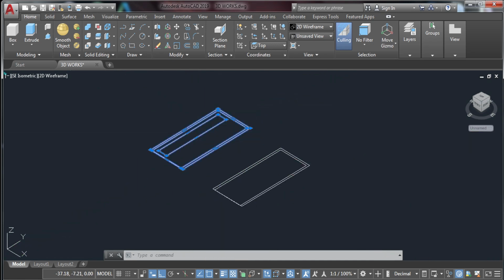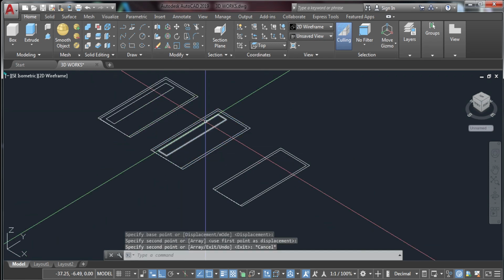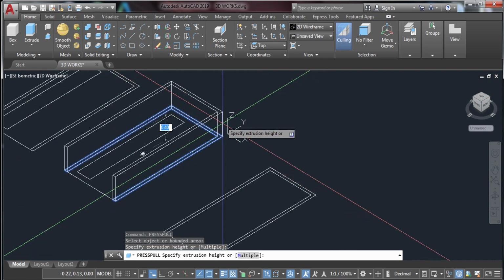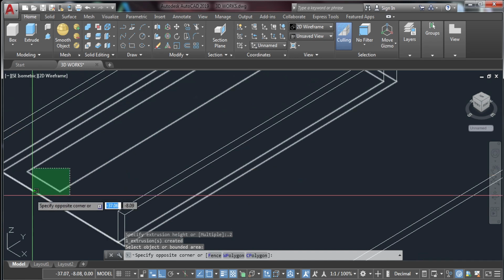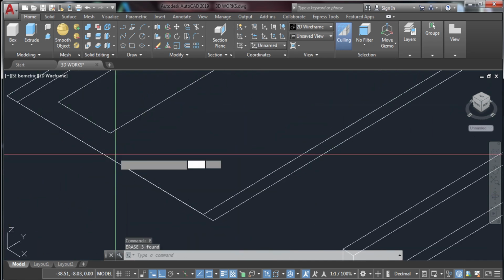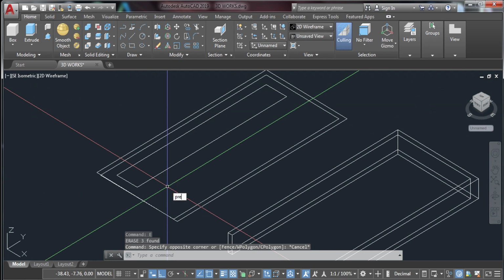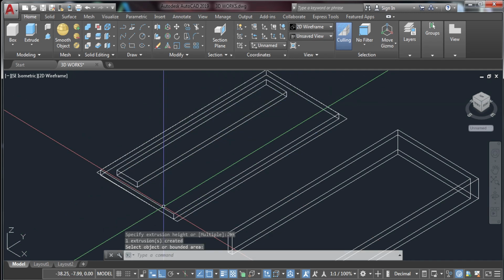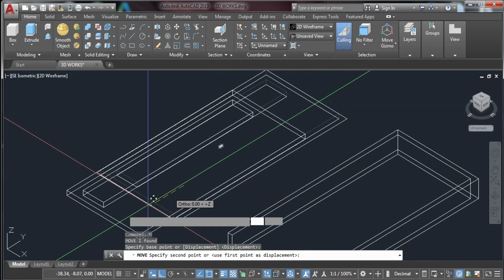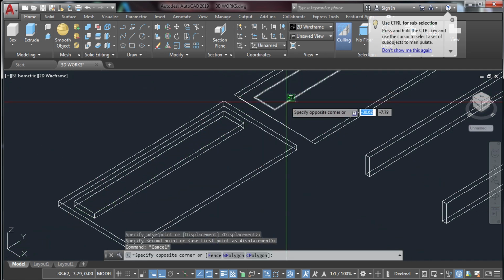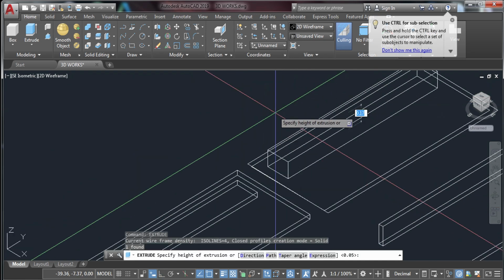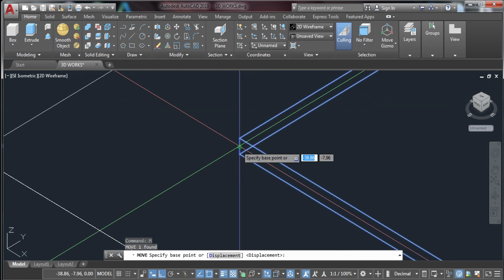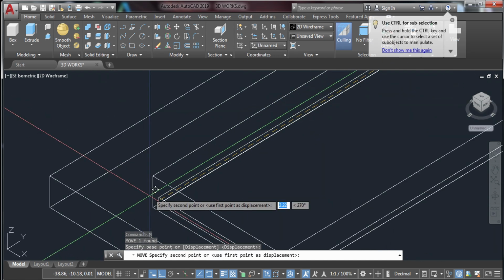So, what I'm going to do here, copy to. Then, type press pull. Okay? Press pull, highlight this door jamb, and then I'm going to type 0.2. Erase this one, and then I'm going to give this a press pull also sa pintuan. Press pull, and then a size I'm going to give here is 0.05. And then move this object pababa, and then another extrude or press pull pa rin dito, 0.01 for the glass. So, move natin to siya papunta rito, and then place it in the middle.